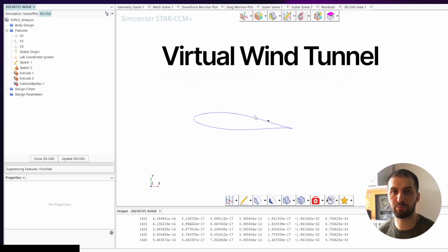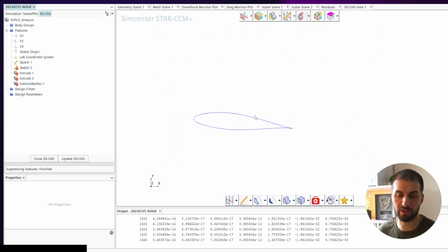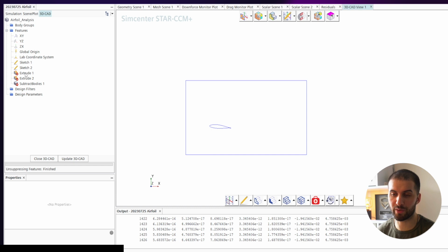And there's a few best practices. So for example, how big does the box have to be so that the boundaries of the box do not influence the fluid flow behavior around that airfoil. There are even a few publications, papers around it. I think even not a few, but a couple of hundreds or thousands of publications talking about this.